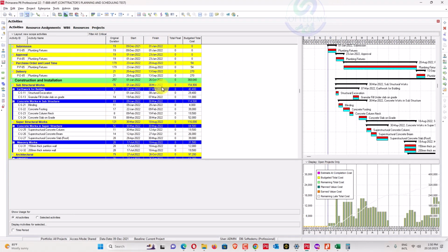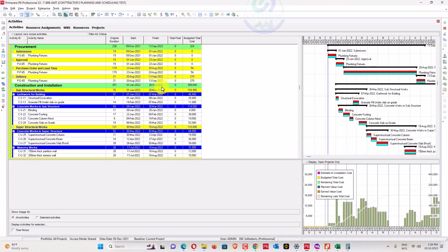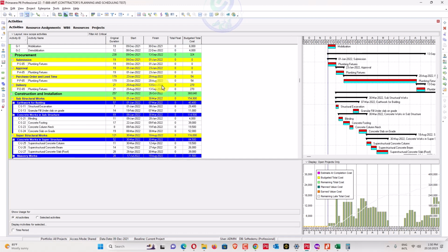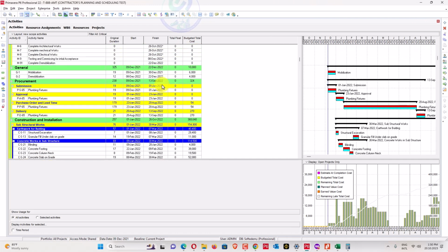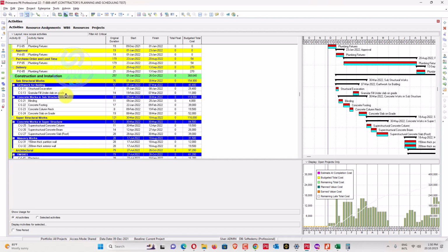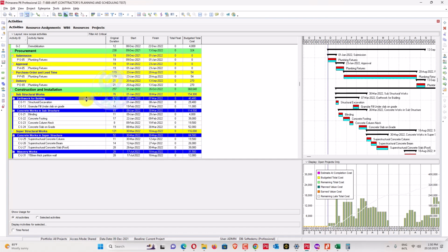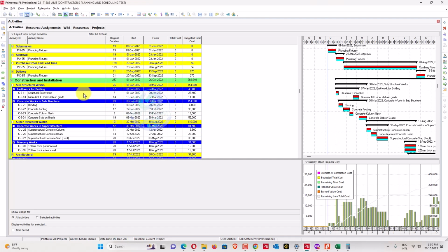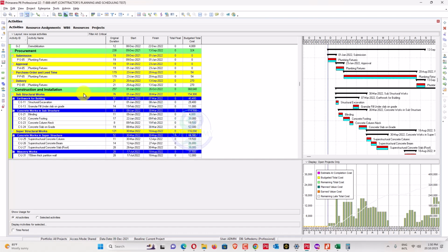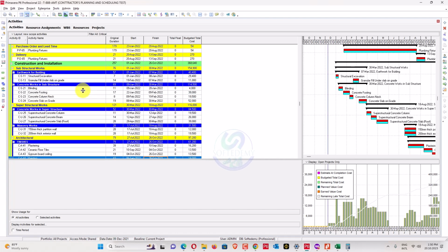There may be one or more critical paths. So what are the common characteristics of those? Mostly procurement and engineering are on critical paths, and then the construction phases which are dependent on them are critical. In this case, after procuring these items, maybe plumbing is more critical than others. You can also maintain other activities by maintaining their zero float.